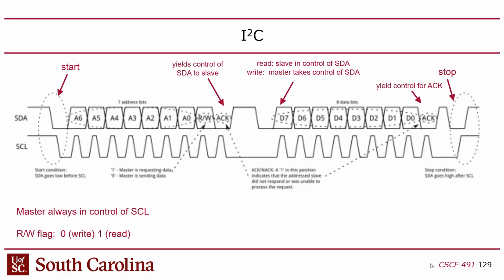But during the transaction, you never change the data when the clock is high. You're not allowed, because if you did that, it would prematurely end the transaction. They would just say, oh, I'm done, and end it. So don't do that unless you want to end the transaction, right? All of this data is changing, and then once the data is established, we go up and down.